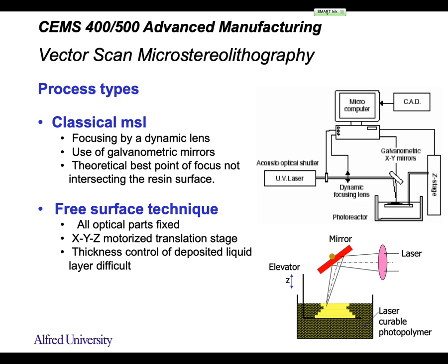So if you want to use it for macro stereolithography, what kind of modification do you have to do? Spot size. To focus is spot size, right? You want to add in some optical elements to focus it. The lens, maybe not simply with one lens, right? An array of lenses, but actually the goal is to minimize the spot size. What else? Is that all, if you want to develop this machine?